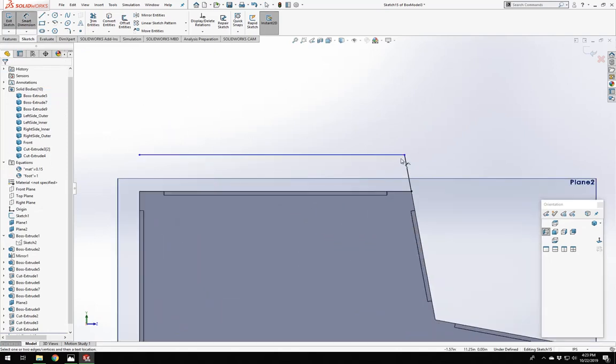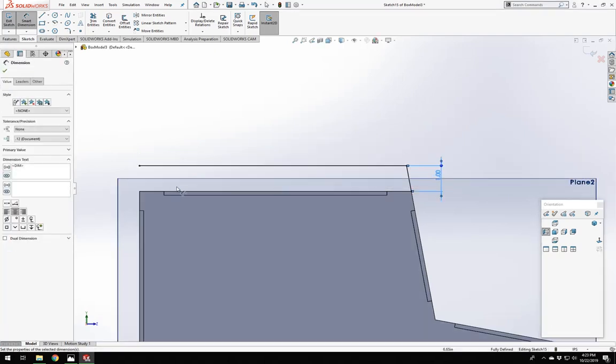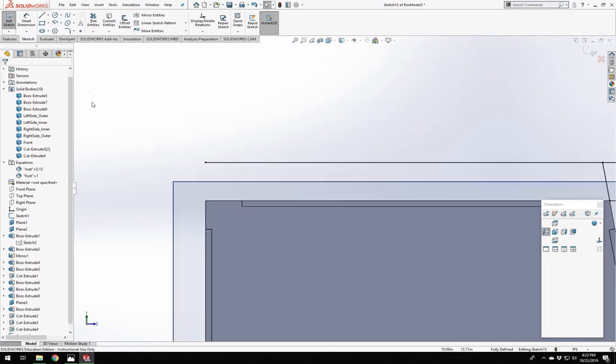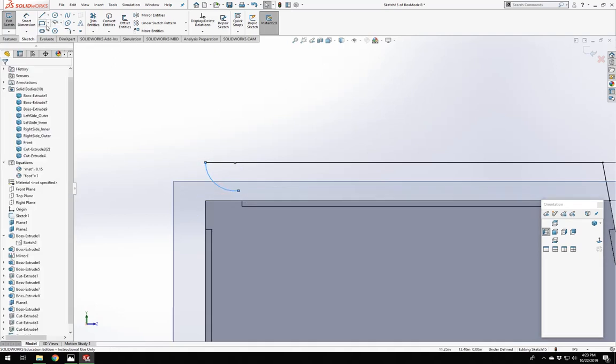We're going to give some dimension going on. Let's do 1 inch. But we're going to need this whole piece to rotate up. And it can't do that if it's just square on the back. The corner will impact. And so what we're going to do in order to sort of resolve this issue is just throw a radius on it. So something like that.